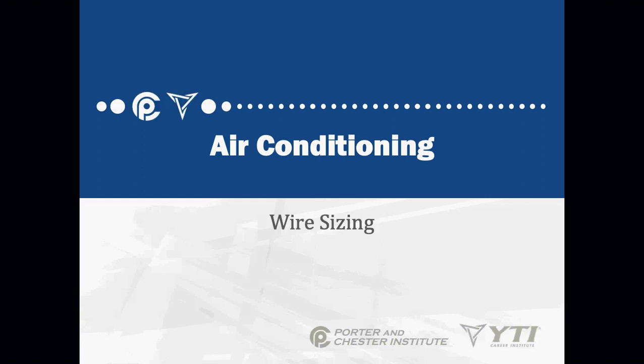Again, you have a wire size for 20 amps. That's the maximum current breaker in there, except for... What was that? Yeah, you'd replace the wire and then maybe replace the breaker. Yeah, too many people. And that's why we actually cover this these days. Too many people believe that the solution to a breaker blowing is to upsize the breaker.